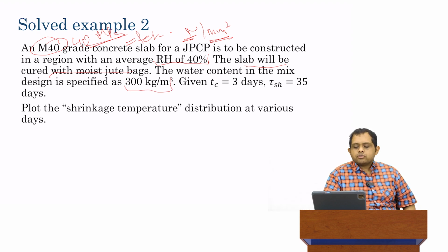Again, I encourage all of you, certainly those of you who are civil engineers, to take a course on concrete technology. You'll see how these mix designs are done. But generally in a mix design, we specify what is the weight. So mix design is done volumetrically. We specify that for 1 cubic meter of concrete, what is the weight of different components to add.